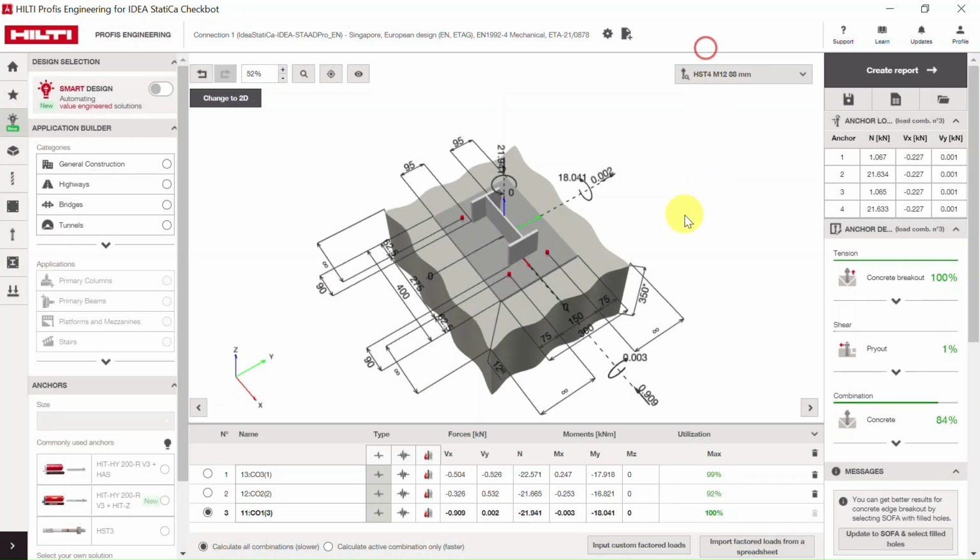One of the other noticeable features of the Checkbot integration is revision management and handling. What you can see here is that the node number was 1, and hence the connection number is also named 1. This means that in future, if there is a change in the loads in the STAAD profile and you update the Checkbot file accordingly, but the node number remains intact, then if you come here and update the loads once more, this file will just get updated.